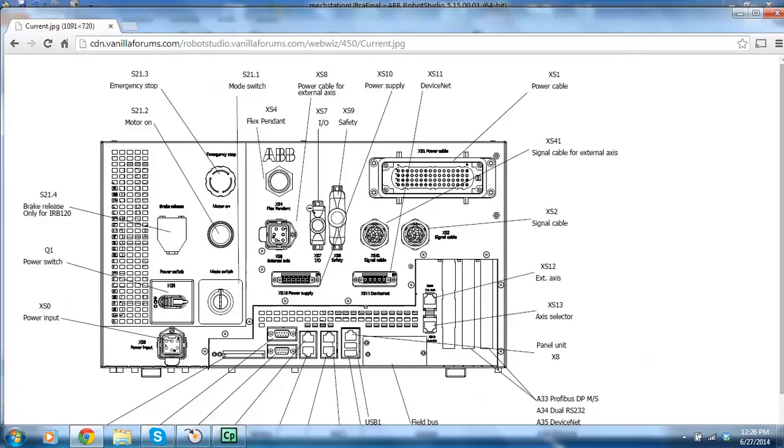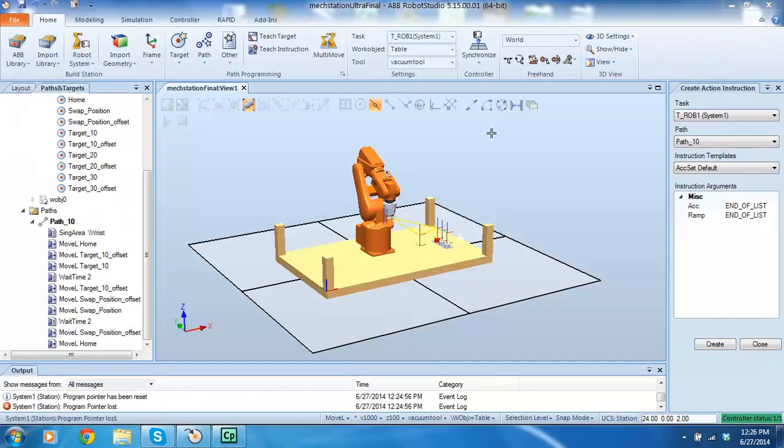And what we've done is we've done a bit of the work for you. We took that connector out to a breakout or a terminal block that you've used before, something very, very similar to the Festo MPS. So we have this cable which goes to a terminal block, so we have our own inputs and outputs. So it's kind of like a PLC.